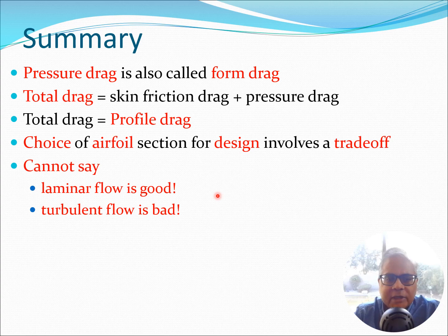We cannot really say that laminar flow is always good and turbulent flow is always bad, because as we saw, the turbulent flow can sometimes be good for flow separation. It can retard flow separation. Turbulent flow is more robust to flow separation, and laminar flow may be more prone to flow separation. These are things we need to keep in mind based on the design we are doing. In many cases, a turbulent flow situation may be preferred, because we know that the flow is likely to separate anyway. So the turbulent flow is going to be more robust to flow separation in those cases.